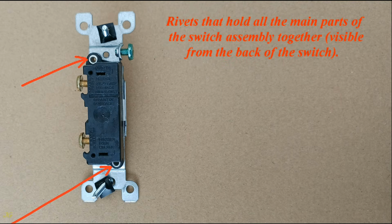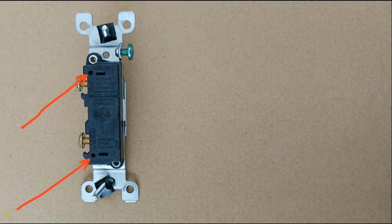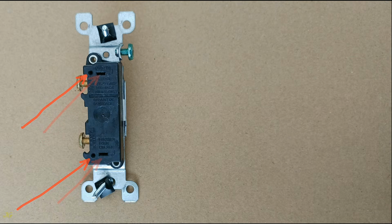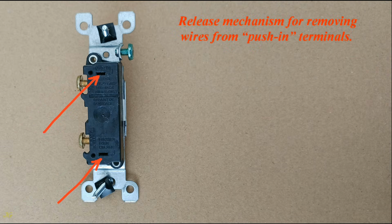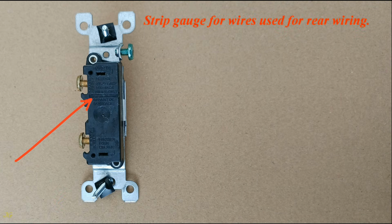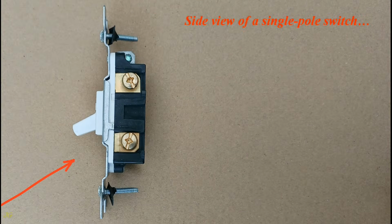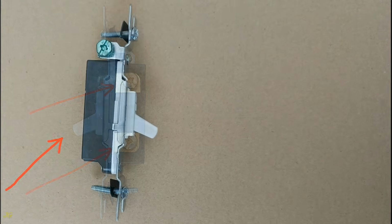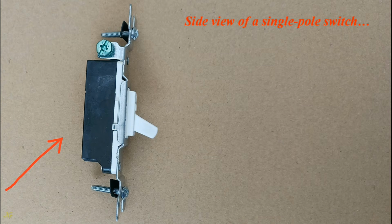Rivets that hold all the main parts of the switch assembly together, visible from the back of the switch. Push-in terminals for rear wiring that accepts 14-gauge solid copper wire only. This type of wiring is not recommended as it does not provide a good connection. Release mechanism for removing wires from push-in terminals. Strip gauge for wires used for rear wiring. Side view of a single pole switch with hot terminals. Side view of a single pole switch with ground terminal.